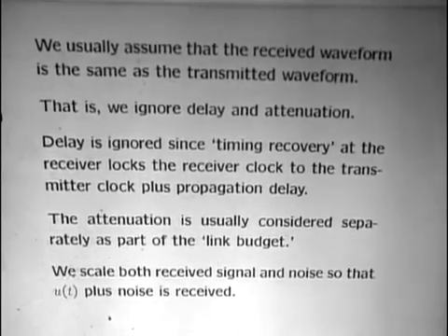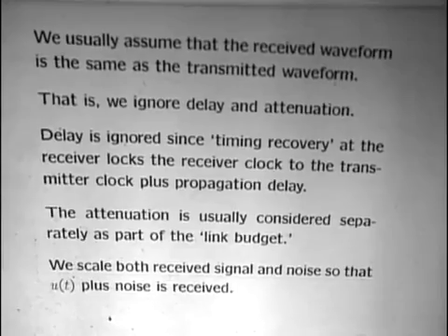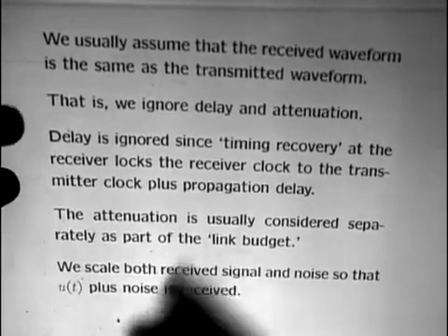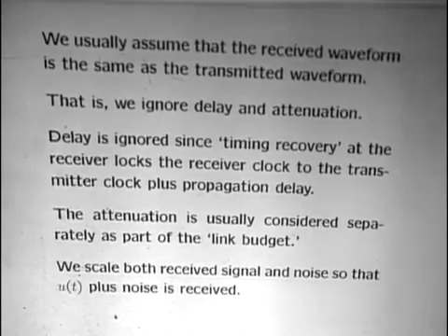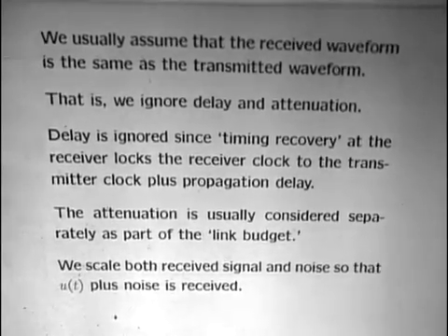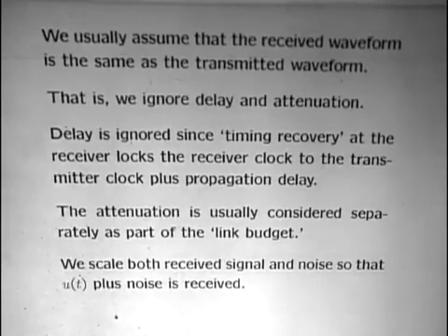After you think about it once, you then accept this as a layering decision. You ignore delay since the timing recovery locks the receiver clock to the transmitter clock plus the propagation delay. And in fact, it can lock the received clock to any place that it wants to lock it to. So we're going to lock it in such a way that the received signal looks like the transmitted signal. And the attenuation is really part of the link budget.